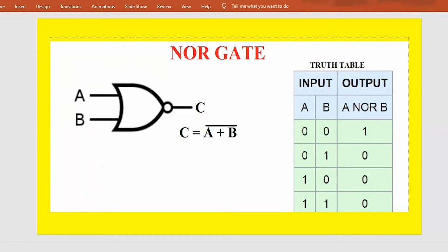NOR is a functionally complete operation. NOR gates can be combined to generate any other logical function. It shares this property with the NAND gate. By contrast, the OR operator is monotonic, as it can only change low to high, but not vice versa. Also, the original Apollo guidance computer used 5,600 integrated circuits, each one containing only 3 input NOR gates.